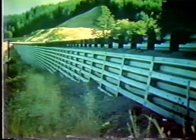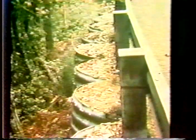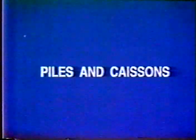Metal bin wall, that's another cellular type wall, as shown here. It's been used quite often. Now, here's another type of wall. It's just used in culverts, probably 30 inches in diameter, but they're stacked and backfilled with gravel or whatever's handy. But it could be a very simple solution to a small landslide using this type of thing. Now, I think California has developed some pre-engineered, you might say, design standards for this. But anyway, that could be a very good solution.